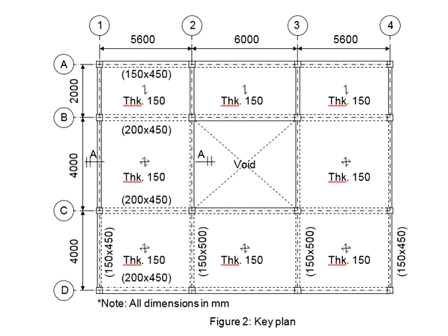The deflections is likely to occur at the shorter span. That means when this is the shorter span, the bending of the slab will be more critical in these directions. The directions of bending will indicate the existence of the bending moment. In order to resist the bending, you will need to have the reinforcement bar longitudinal to the bending.